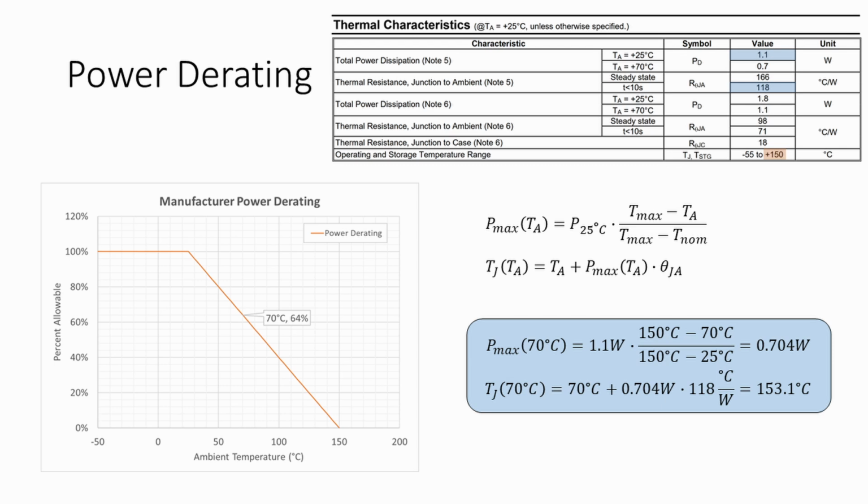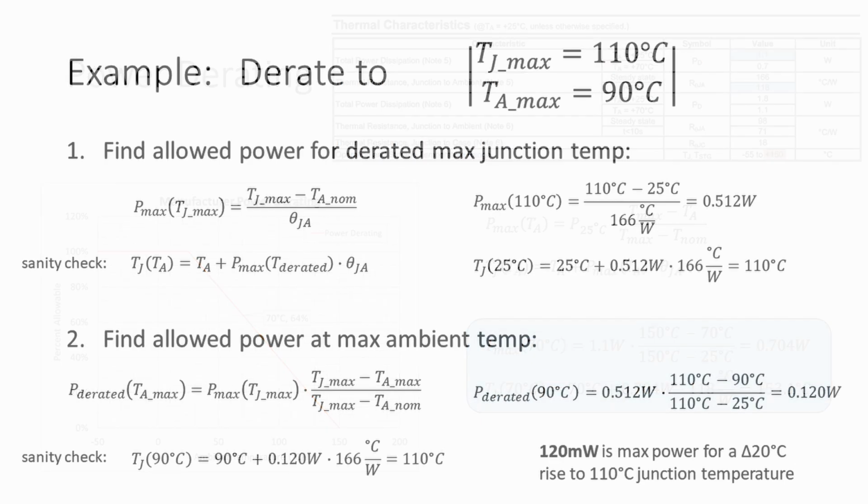To make the design reliable, junction temperature is derated below the manufacturer limit. For high reliability design, like what is suggested in the NASA derating standard mentioned earlier, the max junction temp is minus 40 C below manufacturer rating or 125 C, whichever is lower. So here it's 110 C. Next, we have a requirement for 90 C ambient temperature, which is much higher than the 25 C room temp. So what's the actual power dissipation limit for this part?